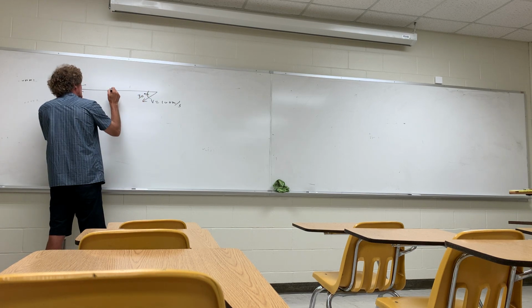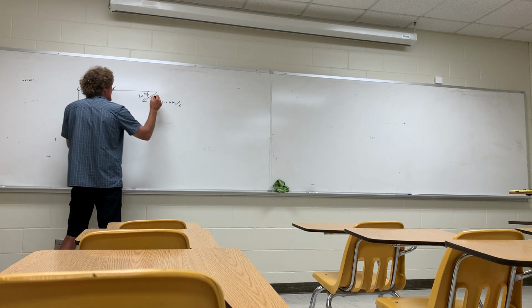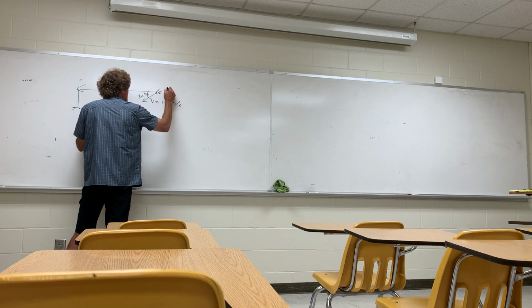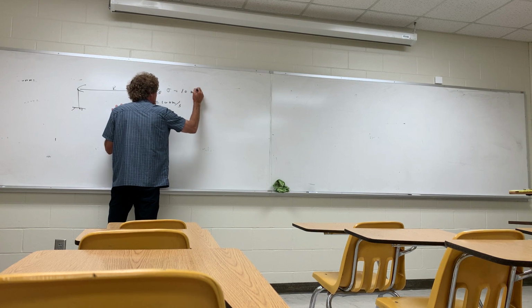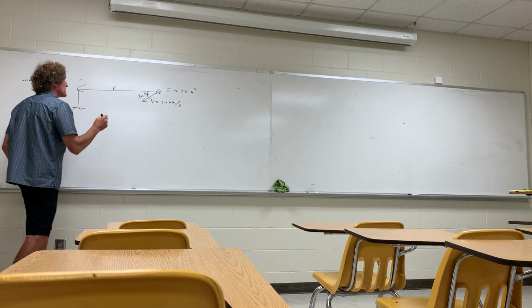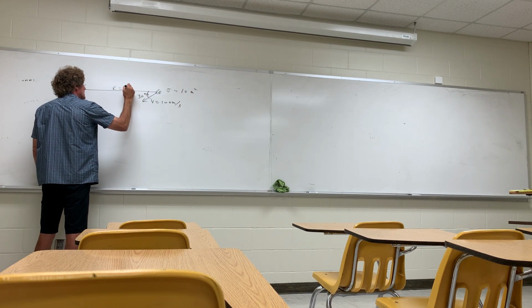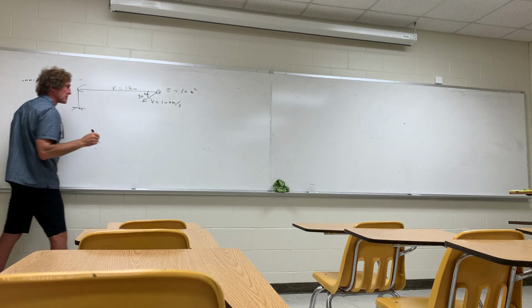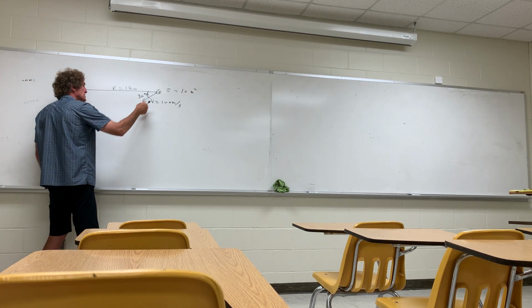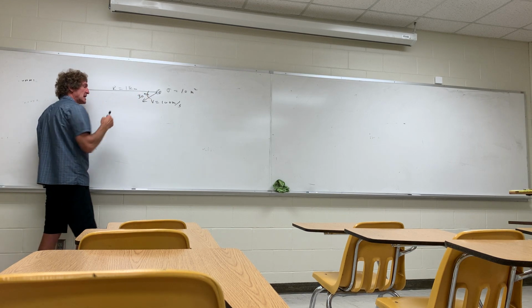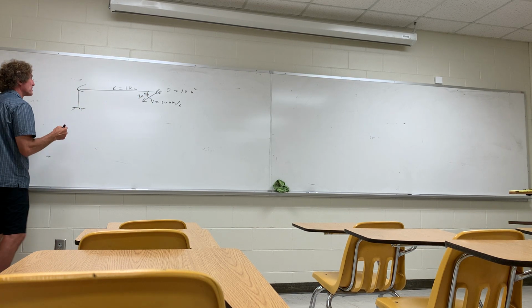This is going to be the perpendicular R, and this is a target with a radar cross-section of 10 meters squared. Let's say the range is equal to 1 kilometer. I'm putting in everything. So this is the actual velocity, 100 meters per second. It's got an aspect of 30 degrees down angle there.